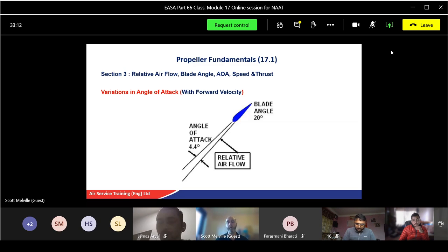When an aircraft takes off, it's a very fine pitch of angle of attack. Lots of power, lots of rotation, not very fast taking off, but it will get there. Once it gets to altitude, once it's got forward speed, they will then coarsen the blade, in other words, increase the angle of attack of the blade, so it just cruises.